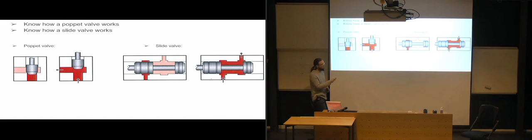With a slide valve, you don't have full closure, so you do get a little bit of leakage going along the slide, basically. It can both leak into the leakage area, where you usually have a leakage line going back to the tank to catch all of that fluid, and you also have some small trickle going into your components.